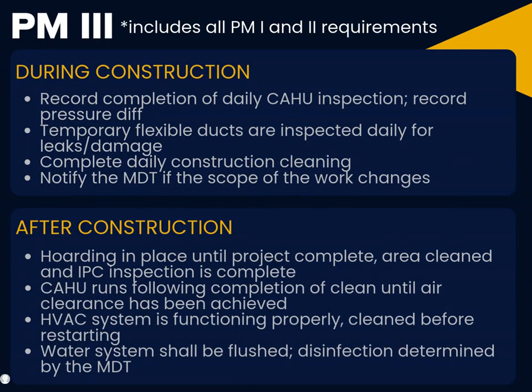During construction, record the daily inspection of the CAHU. Check temporary flexible ducts each day for leaks or damage. Keep a monitoring device running that constantly shows the pressure difference between the construction area and occupied spaces and record it at least once daily. Clean the construction site and adjacent areas daily. Let the MDT know immediately if the scope of work changes.